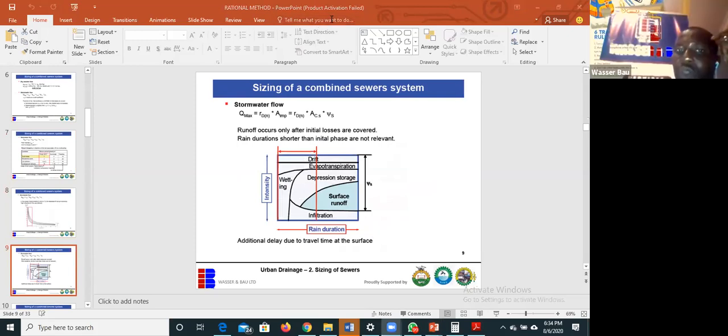So you choose the duration, you choose the return period. Now, this place just tells you how we came about the peak runoff. We came about the peak runoff by considering this is the percentage that's contributing to runoff. This is the amount of water that fell here. But the amount that is actually runoff, that 37%, is this green one. Because the other percentage will infiltrate, the other percentage will wet, the other percentage will depress storage, the other percentage will drift, the other percentage will evapotranspirate.